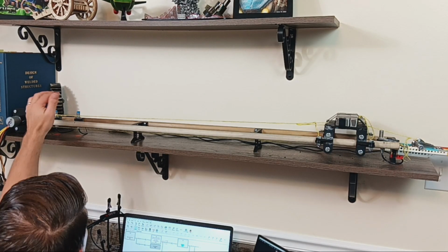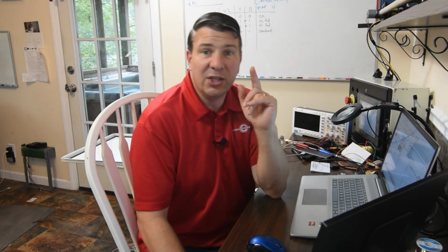All right, the second one here is, you've coasted too far. We're actually going to brake it. We're going to do that, not mechanically, but electronically. Don't get all excited. It's not all that thrilling. What we're going to do is turn our motor into a generator and put a resistive load on it. In our case, it's going to be, I think, 7 or 8 ohms. So pretty high resistive load. It'll almost lock that thing solid.